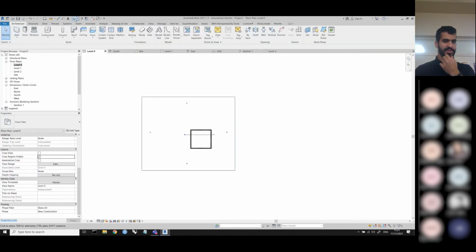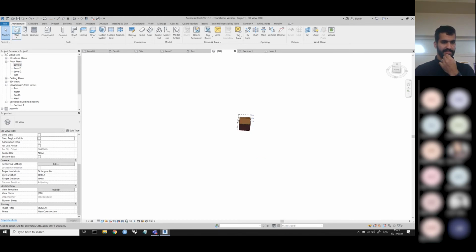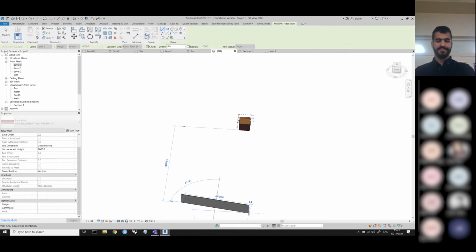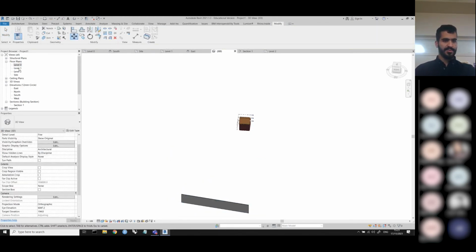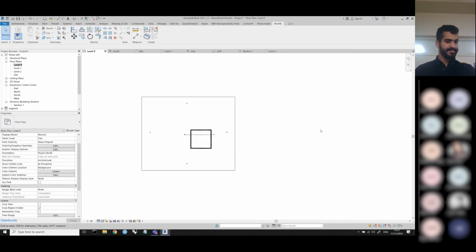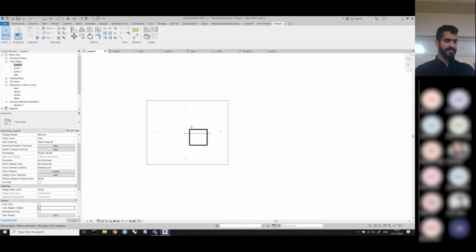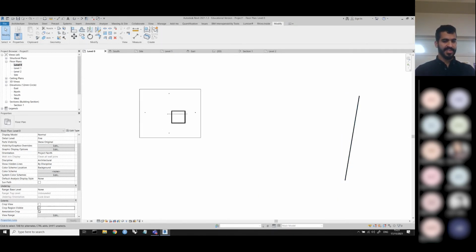So I'll try to demonstrate. Here, I'm drawing a wall over here, right? And I go on level 1, and I can't see it. This is a default view. It's because there's a hidden viewport. This is the viewport. I open it. I enable it by clicking on this, apply, and then, well, I can still see it, but apply. But this crop view, if I click on this, apply, it'll crop everything outside of it.